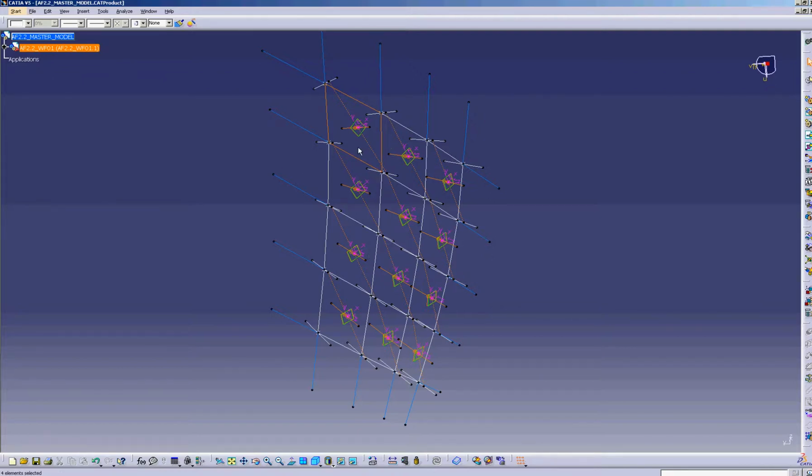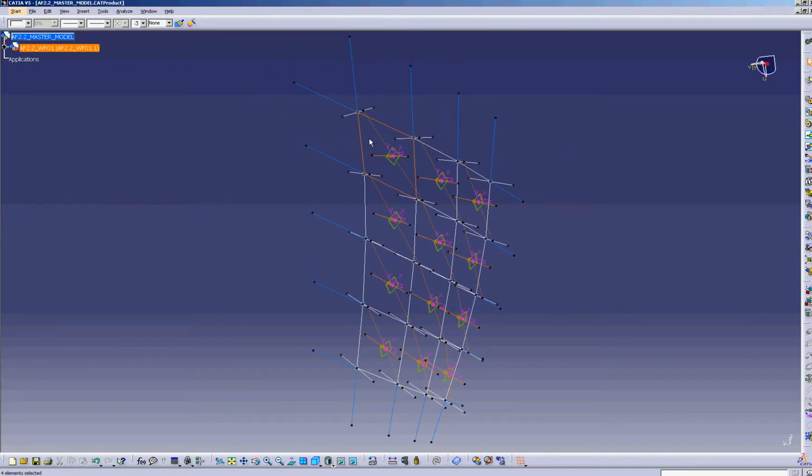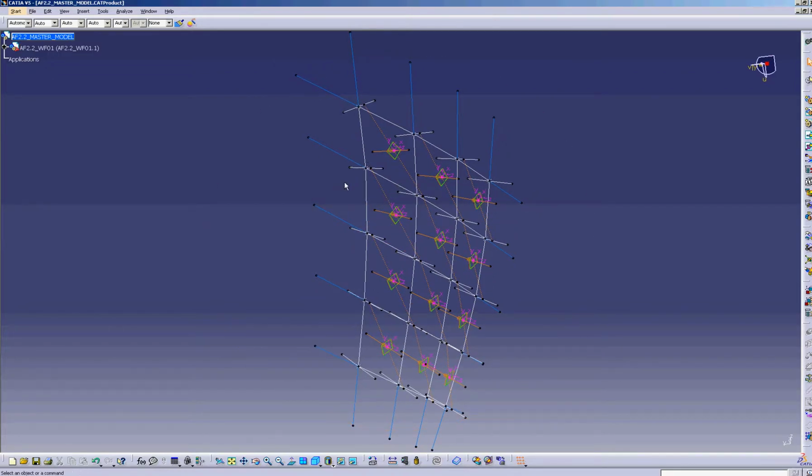into this wireframe. And when you do that kind of reuse in CATIA, you're able to bring along drawings. You can bring along a lot of functionality that CATIA has in the product context for reuse. So it's a little bit like some of the other concepts in reuse, UDFs, power copies that we dealt with earlier in the semester, except we're sort of scaling it up in complexity, and that we're able to take an entire assembly with a wireframe and 15 different parts and some drawings and whatever else we want to put in that assembly, and instantiate that as a component across this facade.